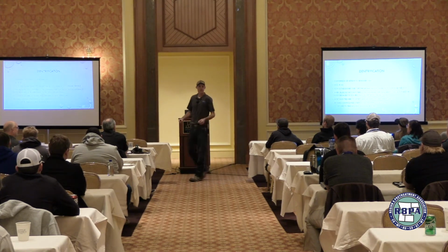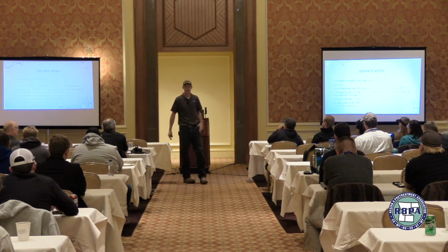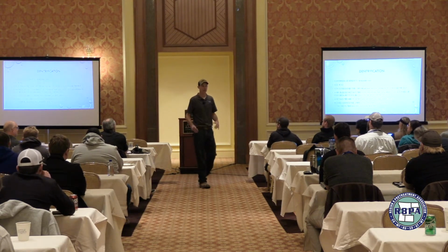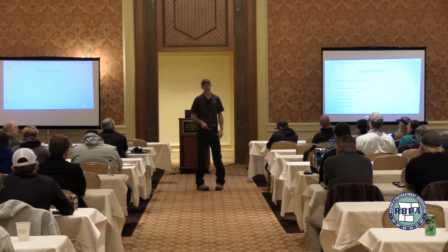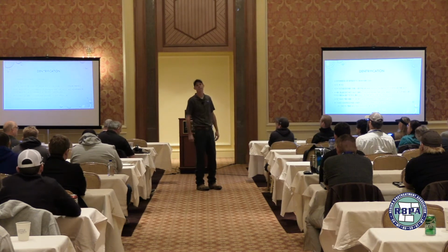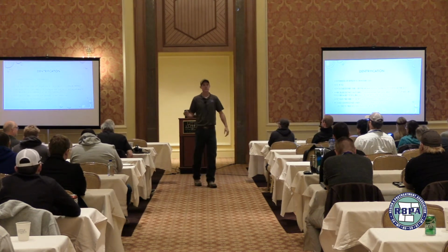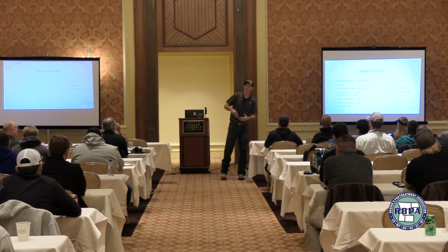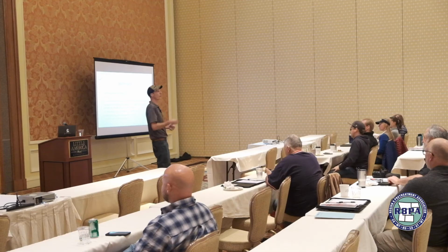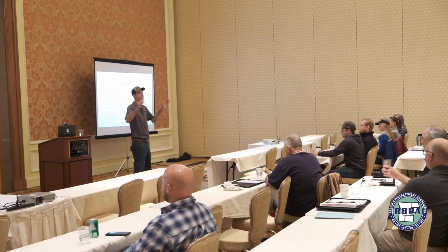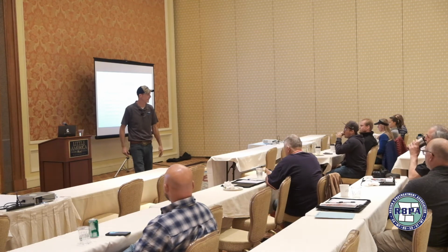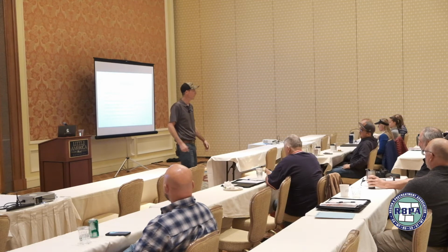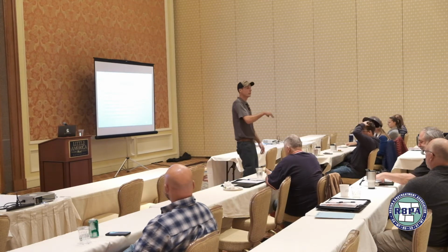The VFA production is for a whole other set of bugs that we won't talk about today because I get real nerded out there, and then you guys will be, Friday, be like, Dave, just shut up. VFA production happens at that methane fermentation stage if you run that DO down too far, or the ORP down too far. Now, if you just run a DO probe in your process, you'll never know where that ORP level is.